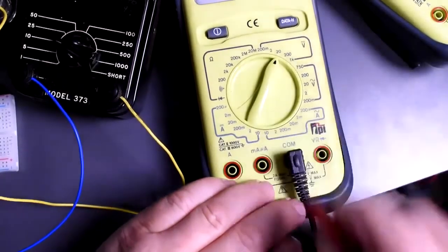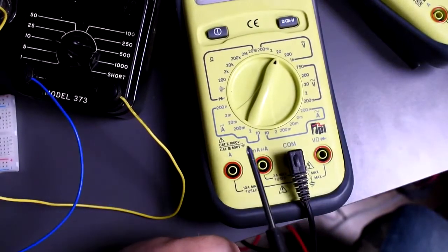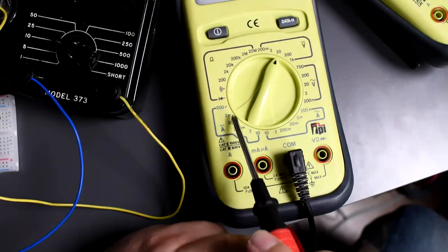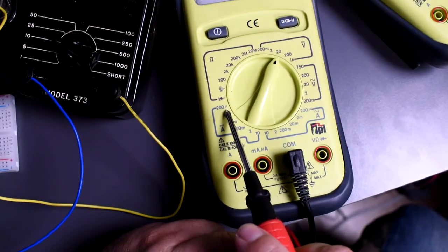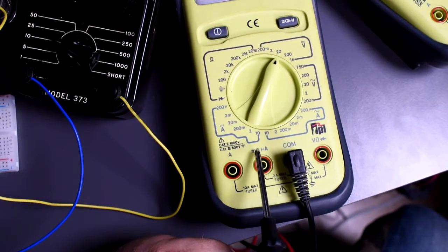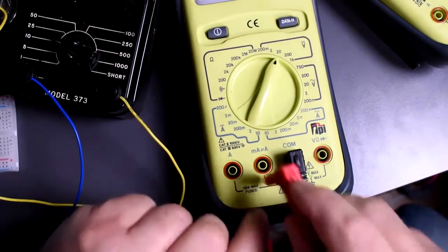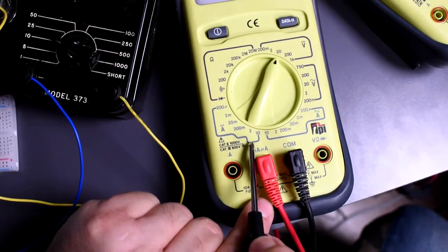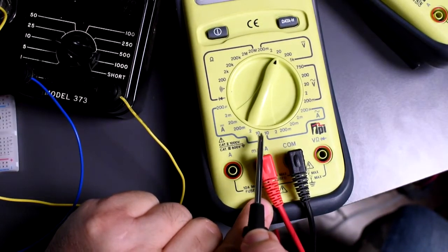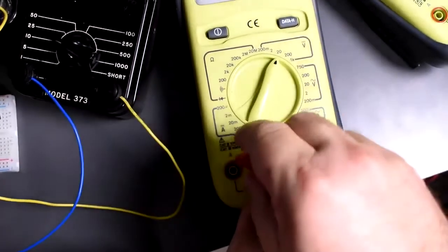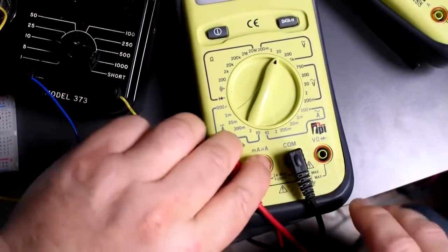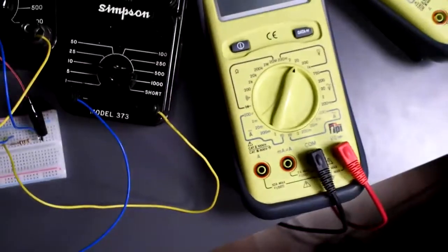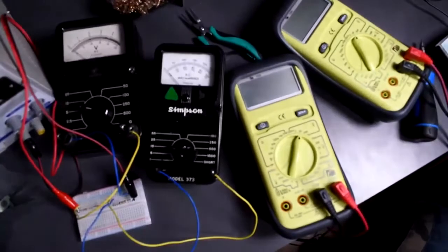If you want to measure current in milliamps, so anything that says milliamps, the range says up to 200 milliamps, up to 20 milliamps, up to 2 milliamps, or 200 microamps, that also fits there. You're going to use this port if you want to measure current. Now, if you want to measure current not in milliamps but in amps, so this one says up to 2 amps, up to 10 amps, you're going to use this port right here. So that's how this particular meter works. Of course, different meters might differ in some way, so you're going to have to know your own meter, okay?